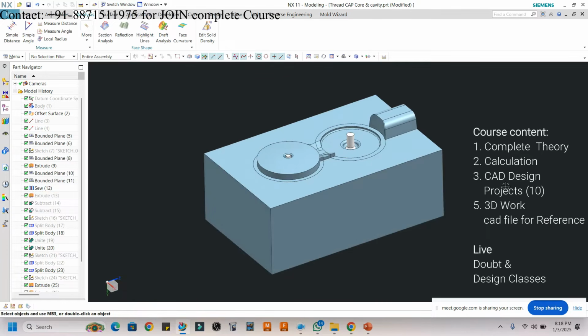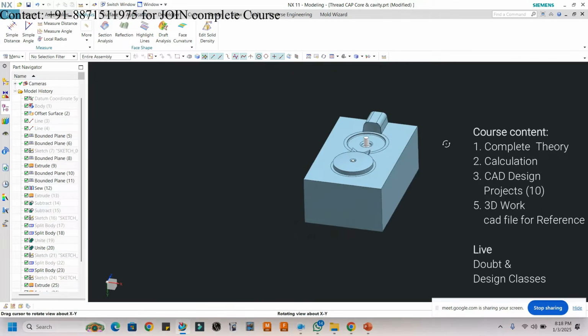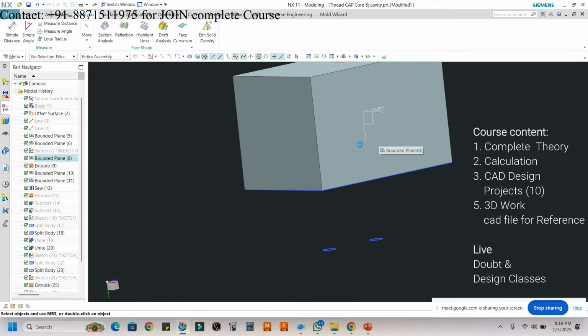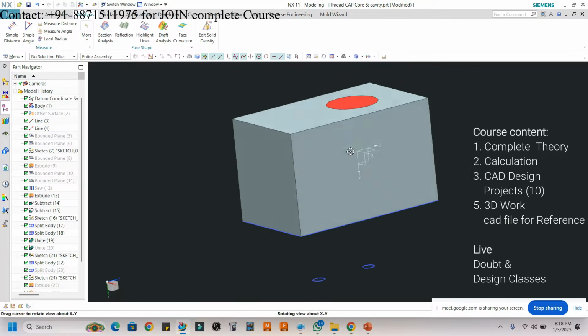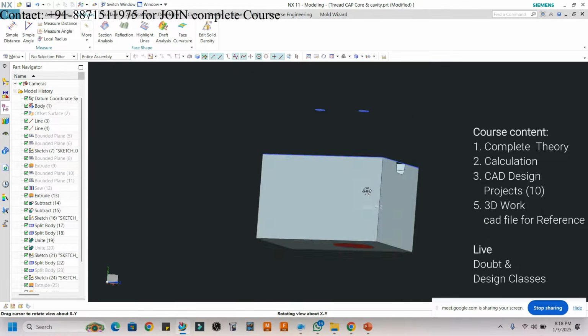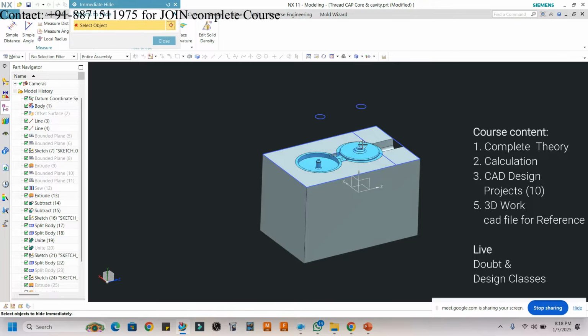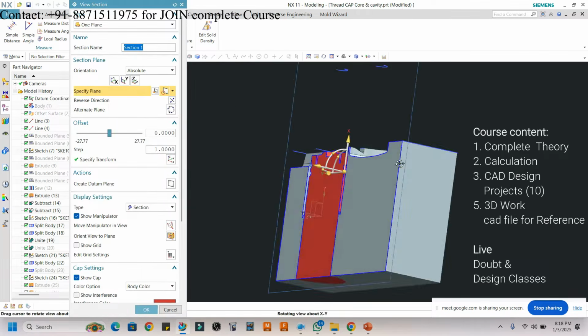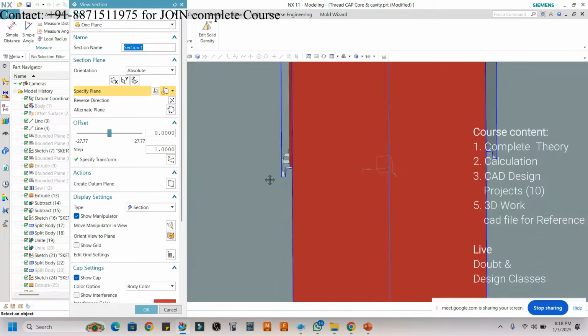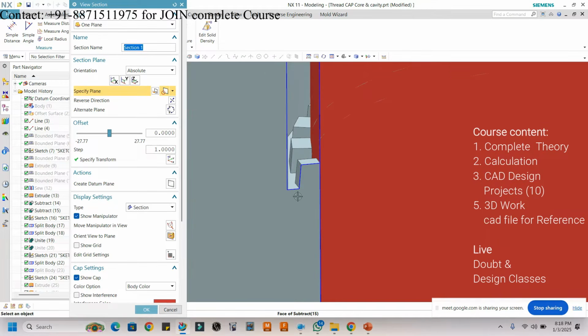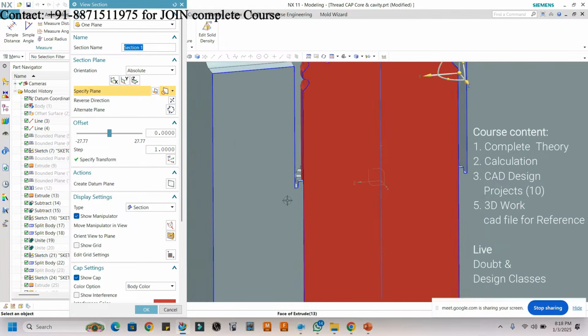We have to incorporate the local insert into the core or cavity insert, right? Yes. Now you can see that this is the cavity portion, and this is the core portion. Here I am hiding just the component, and here just take the section view and see what is happening. Here you can see that it is the teeth, which is the part of the core.